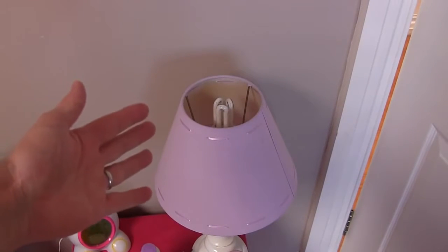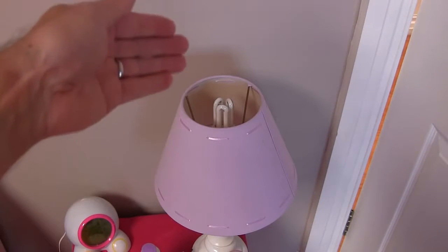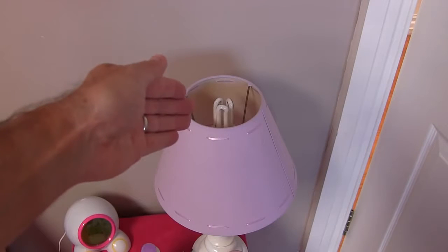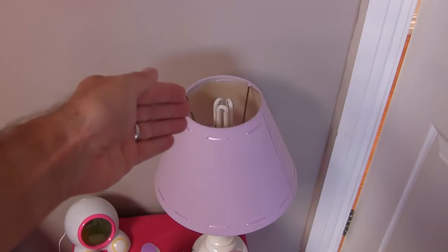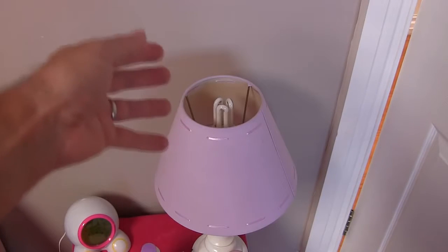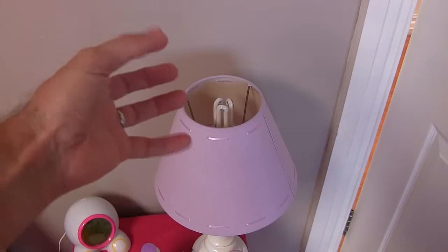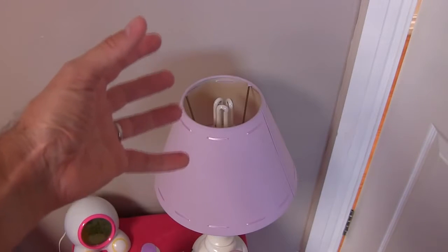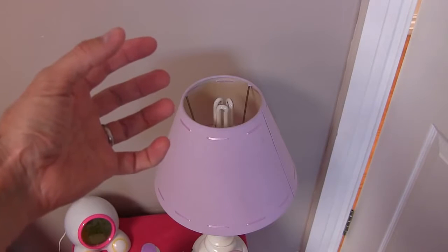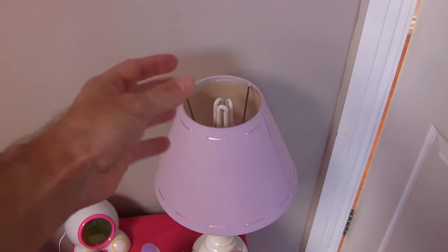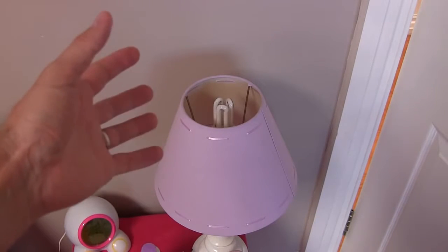Again, things like bedside lights, one serious consideration is the CFL globes. You might have a standard 60-watt incandescent globe in there, and you can easily replace it with an 11-watt or even lower wattage CFL. The colors are getting better, so you can get far better warm whites in terms of replacing that incandescent, the type of light warmth that comes from an incandescent globe. And also, they are almost instantly on, in that they don't need time to warm up. But those are things to consider.